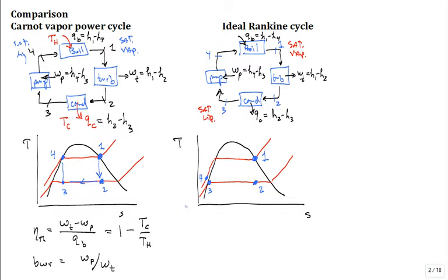It's a lot lower. I then, in the next slide, showed how it's only half a degree C higher. So every time we illustrate this by hand, like I just did, we make T4 look like it's a lot higher temperature than T3. In practice, it's a lot lower delta T. There's a small delta T between T3 and T4: half a degree C, 1 degree C, 1.5 degrees C, small delta T. T4, though, has the high pressure. I mean, the pressure at 4 is high.